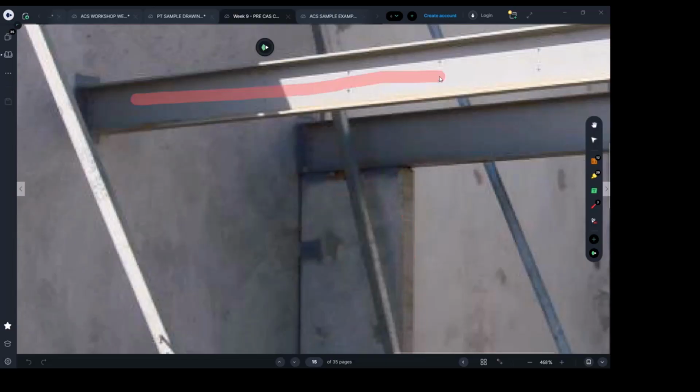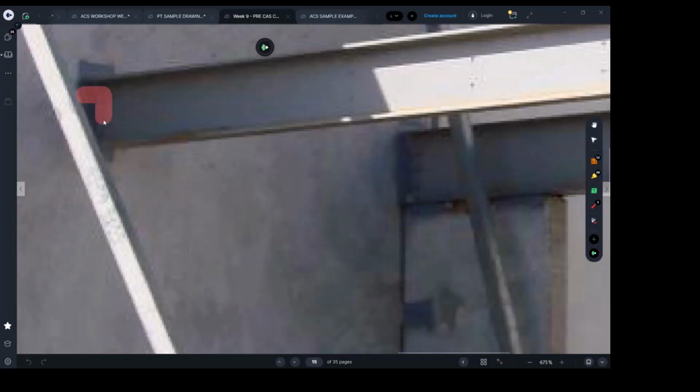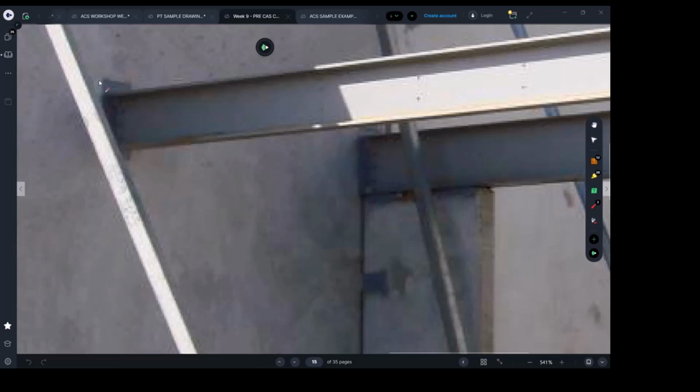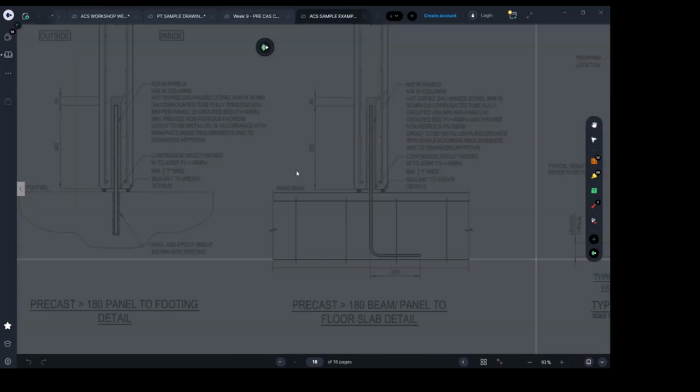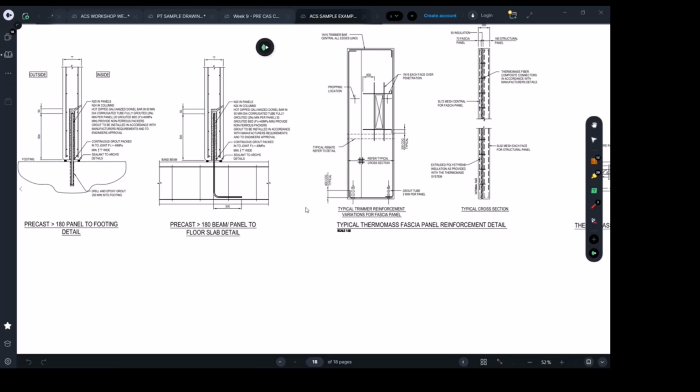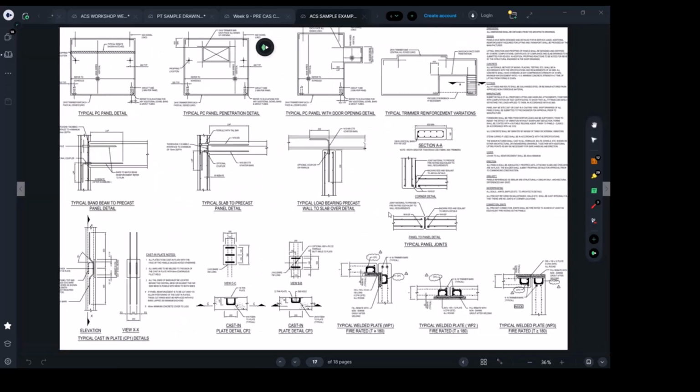But here you can see there's a steel beam which is fixed to a cleat. So there is a cleat here with maybe 2-3 bolts, and the cleat is welded to a plate, and that plate is cast in. So in the back of this plate, you've got those U-shaped bars. If you want to imagine it in a different way, have a look at the engineering drawings I will share with you. We gave you those, and we're going to discuss a lot of details.